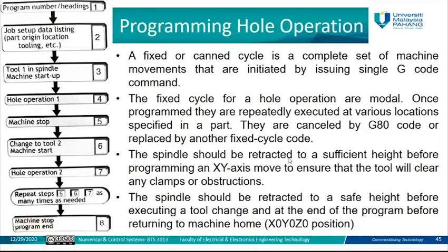When we talk about milling machines, linear profiling is one of the most used codes, G01, and then we talk about G02 and G03 for circular profiling. So you should go through the examples that we highlight and practice how we can use G01, G02, and G03 to build the linear profiling and also the circular profiling for CNC milling machines.